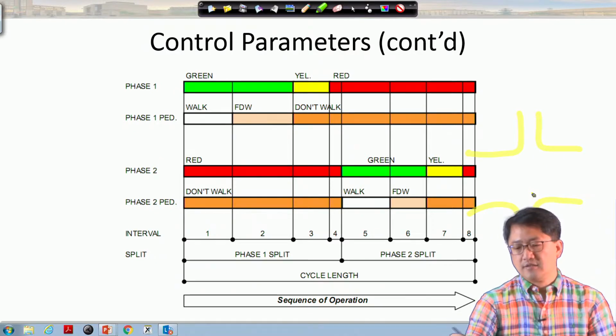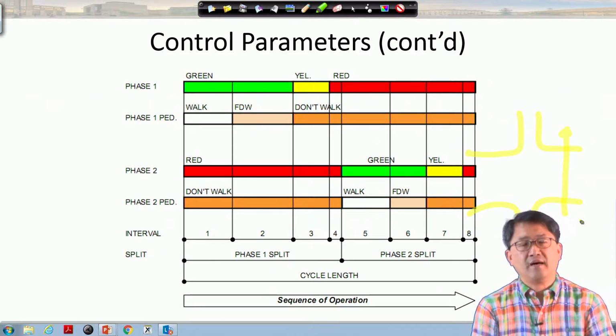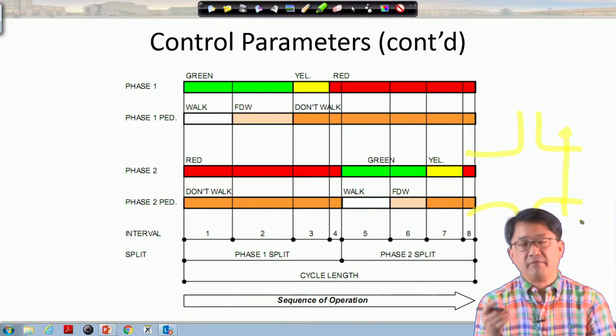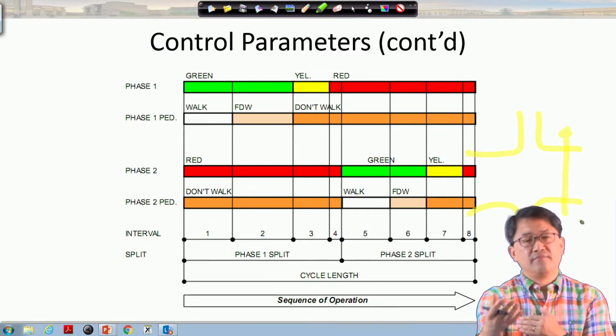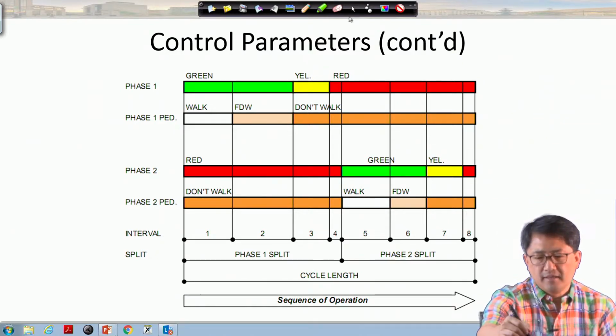And during 15 seconds, they cannot cross the entire street. It's a big challenge. It depends on how many pedestrians or bicyclists you have to serve. If you have a heavy pedestrian volume road, you have to make sure that green times are long enough, even though cars are not utilizing it. Or if it's a low pedestrian volume in the US, they just have a pedestrian actuation button that a person pushes, and then only that cycle provides long enough green for safely crossing the entire road. So that's something to keep in mind.